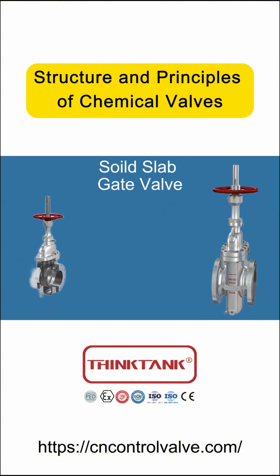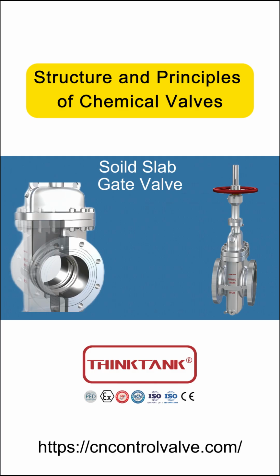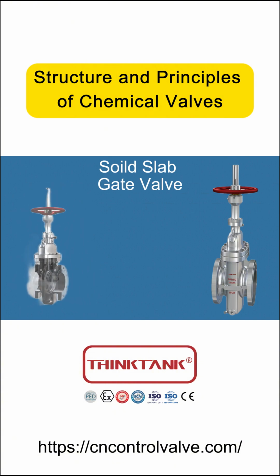A slab gate valve. The force pressing the gate against the seat is provided by the media pressure and the expanding mechanism between the two gates. The sealing surfaces are always in contact during the opening and closing process. This can prevent particles and suspended matter in the media from affecting the sealing surface, achieving a self-cleaning effect. The media pressure will affect the force on the downstream sealing surface. It can seal well even under high pressure and high flow.